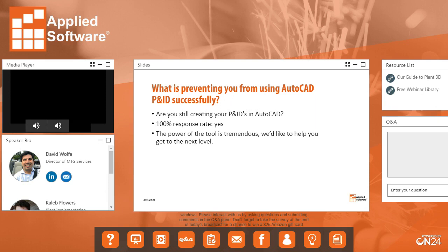However, you can connect these within the drawing, so you can make all these drawings connect together. There won't be quite the intelligence of using Plant 3D, but the information still lines up, so you're not losing everything you had before. And then typically people will just continue on from now on using the smart P&IDs.